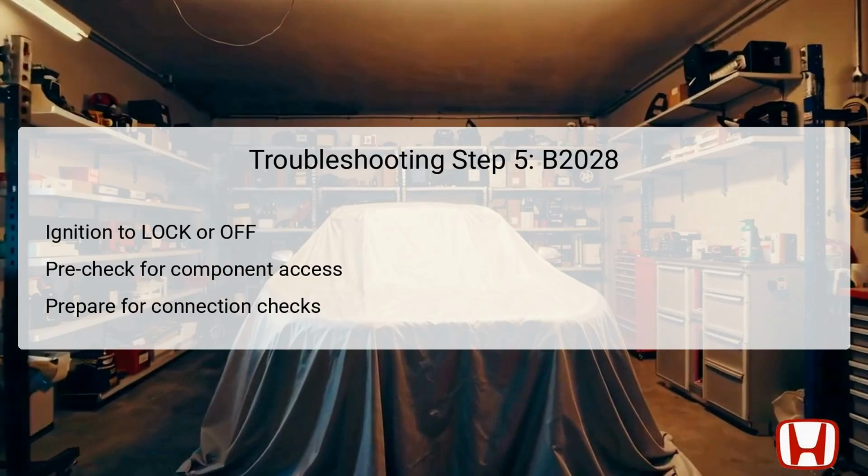Subsequent to evaluation with the HDS, if the B2028 code is confirmed as present, the technician must turn the ignition switch to the lock position or select off using the engine start-stop button. This action is necessary to safely access and disconnect components involved in diagnosing the issue further. By effectively powering down the system, technicians protect both themselves and the vehicle's electronic components from potential damage.